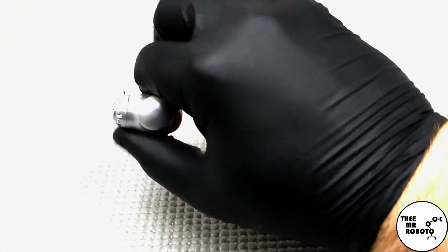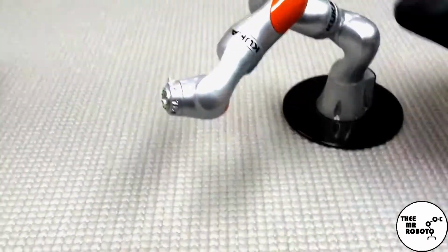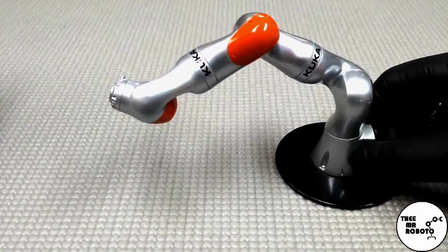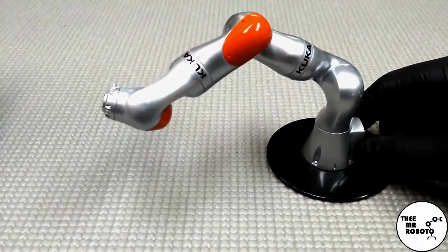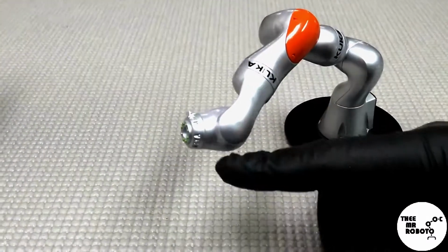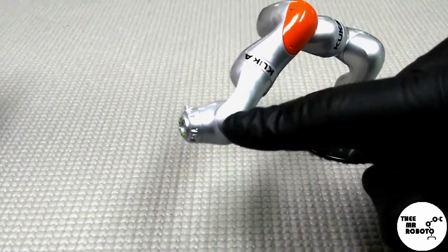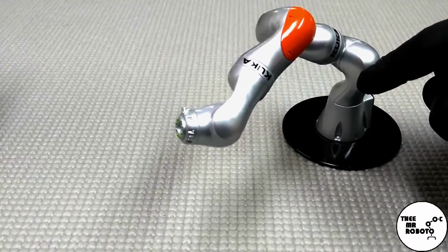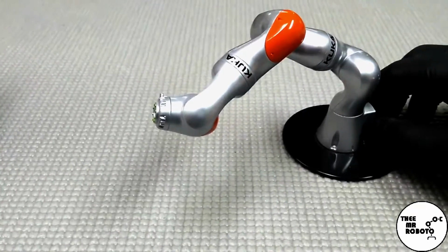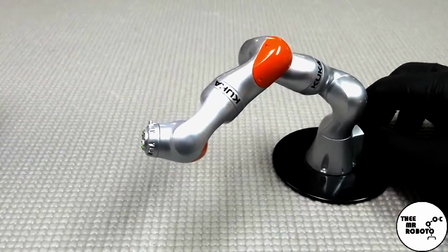Now, those joint angles are important because they make up this coordinate system reference. But if you need to be modifying that position and you just want to change it 5 millimeters in the X, if you reference your position in your robot program with joint angles, you can't change it without going in and re-teaching that position with jogging and point touch-up and things like that. And I'll get into those topics later.